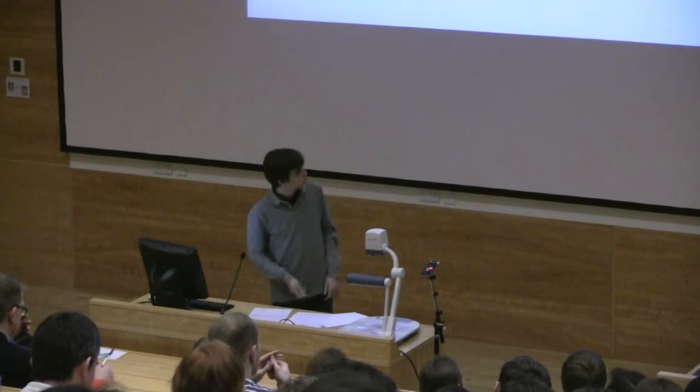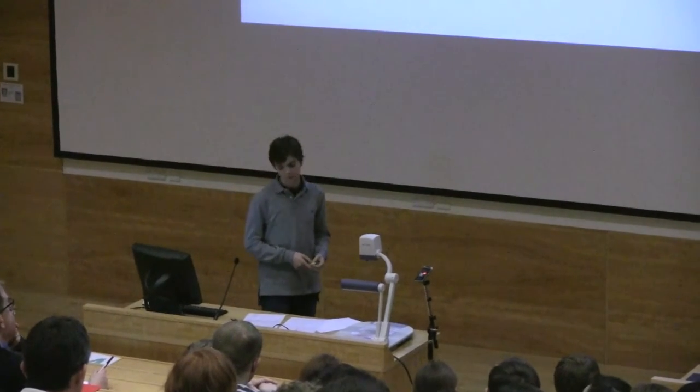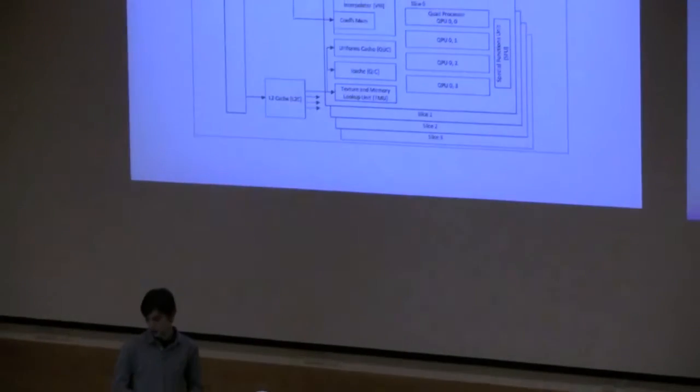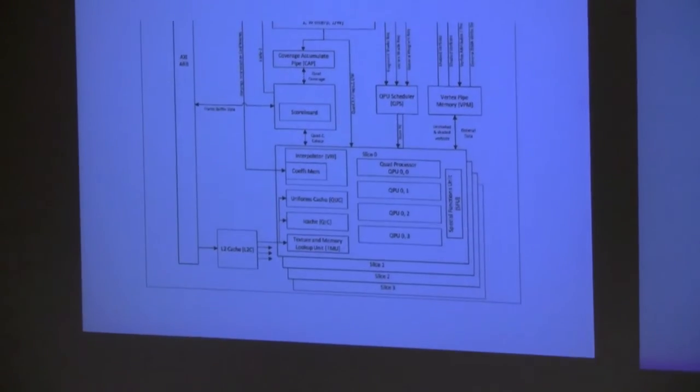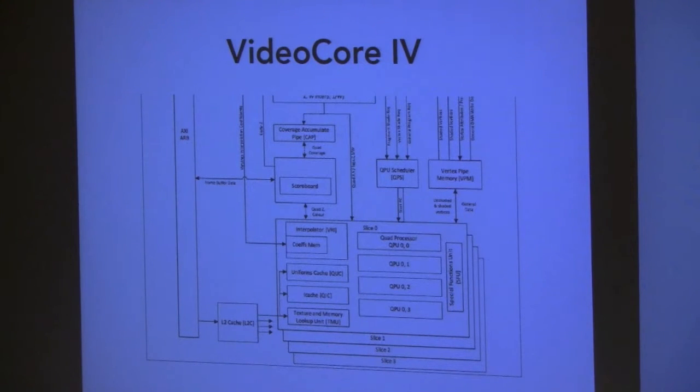Fortunately, what we did have at the time was a fast Fourier transform implementation by someone at Broadcom, which we were able to decompile the shader code for and work out how you could extend that to matrix multiplication and various vector operations. And we also had a mailbox interface in the kernel that let you submit code to the VideoCore to run.